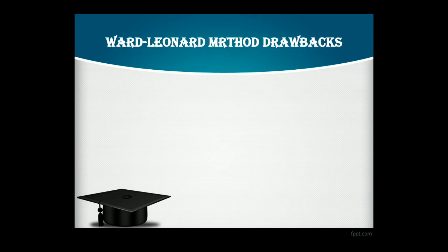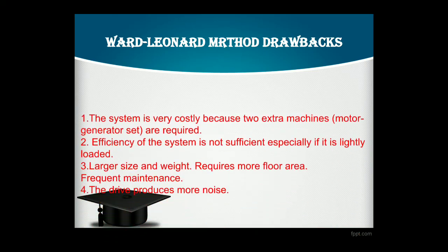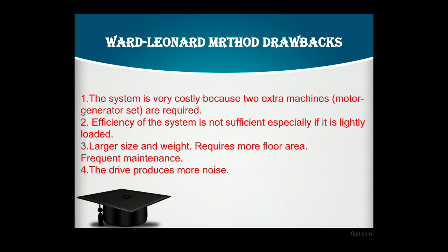Now the drawbacks of the WARD-LEONARD method. Number one, the system is very costly, because two extra machines, an induction motor and a generator, are required. Number two, the efficiency of the system is not sufficient, especially if it is lightly loaded.